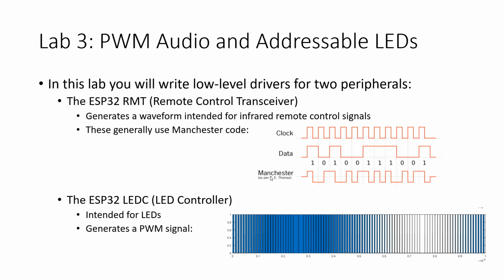Okay, so this is designed for a non-existent technology, infrared remote controls, because infrared remote controls use something called Manchester encoding. And the idea is that this is yet another protocol that is an asynchronous protocol. So if you have an infrared remote, you can't send a clock. There's no clock wire, so you can't have a synchronous protocol. So we got to go asynchronous.